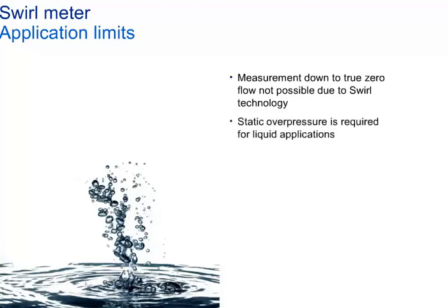The bluff body or swirler constantly causes a pressure loss, which, in the worst case, may create a cavitation in the pipeline. This cavitation is strongly destructive and must be avoided by providing sufficient static overpressure in the pipeline.